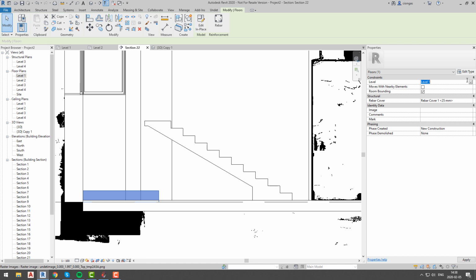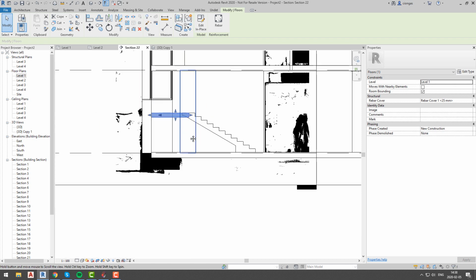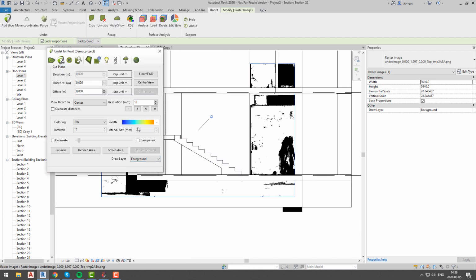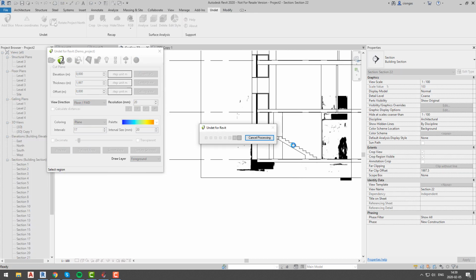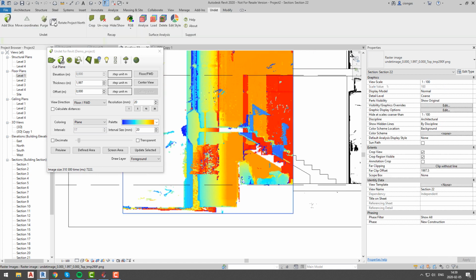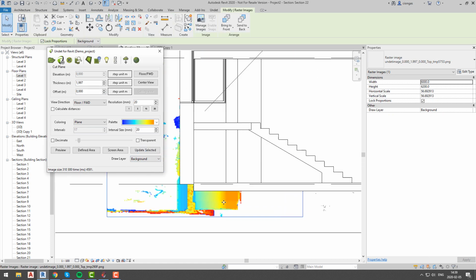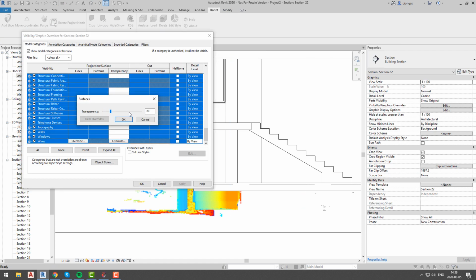From this point it is up to you, how detailed you want your model to be, but it is safe to say, that using dynamic images in sections and floor plan views you will be able to model any object you want either using standard Revit modeling elements or using Model in Place function. In the end of our video, we will use new Undet for Revit feature, and we will check and visualize created models' accuracy based on the point clouds.